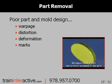When ejecting any part, it's important that we do not distort the part as it's being ejected or introduce stresses that will cause the part to deform in its application. This is why stripper ring or sleeve ejection is used to eject this type of part geometry. It may cost a little more for the mold, but the part would run a faster cycle time. Also, since the force is evenly applied around the perimeter, the part won't distort, and the likelihood of the part becoming marked is reduced.